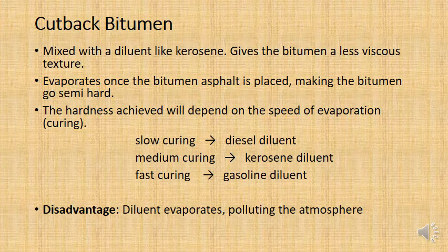If it doesn't matter so much, we'll probably use a diesel or a kerosene. Now the big issue, though, is petrol is very expensive, and so is diesel. So unless we want fast curing, we're going to use kerosene as the diluent, and I think that's the one used 95% of the time with cutback bitumen.